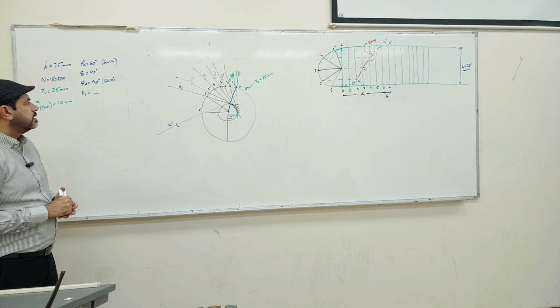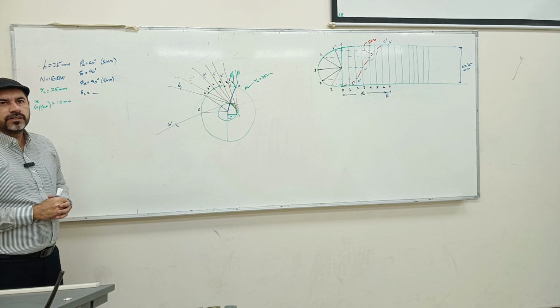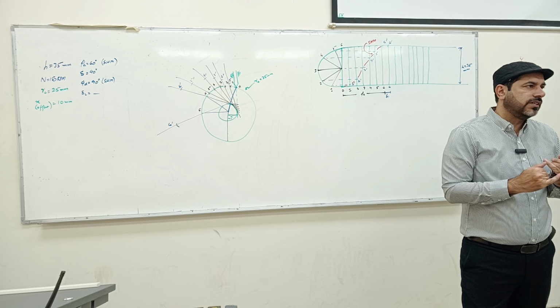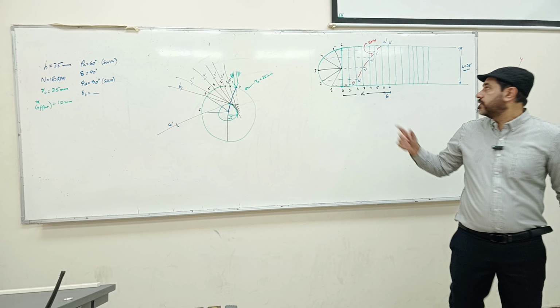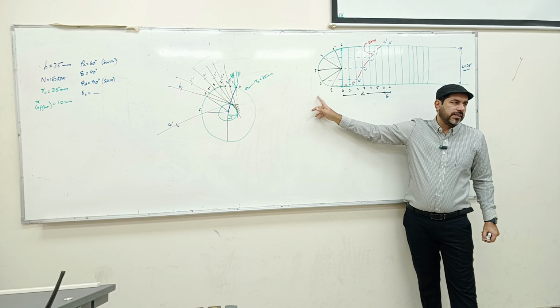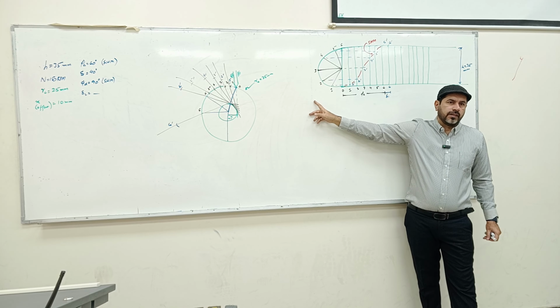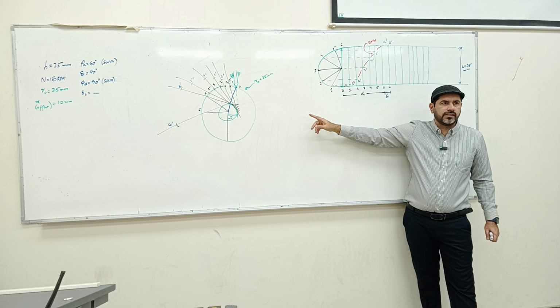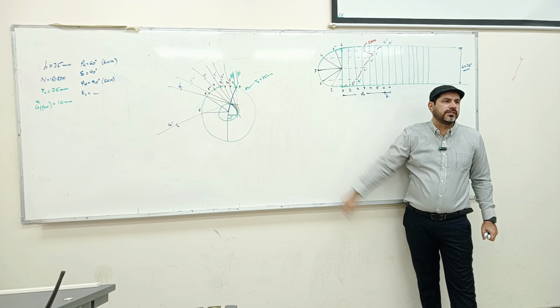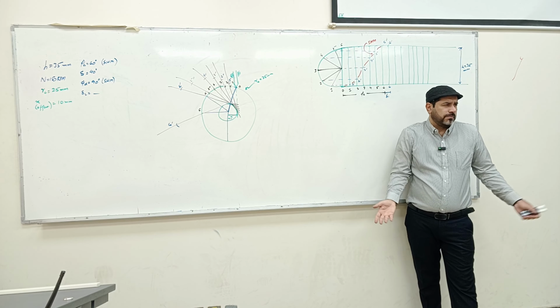Then we go to the downward side for a simple upward motion. Even if you draw irregular spaces, it works because you're taking the reference outside the space of these lines. But in the uniform velocity, because you depend from point 1 to the last point, they all should be equidistant. That's basic geometry.